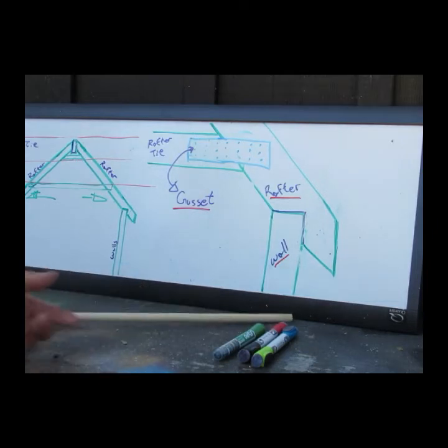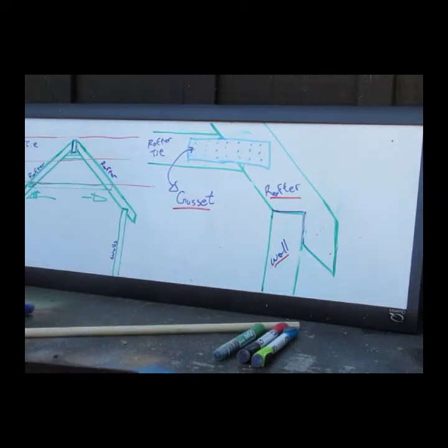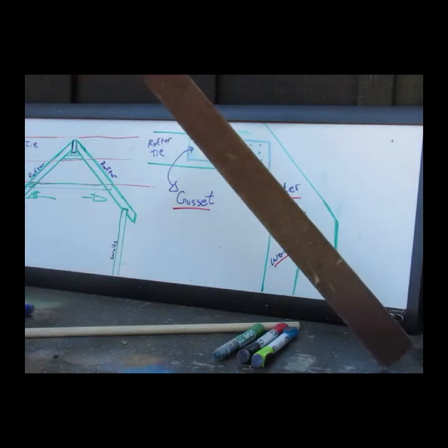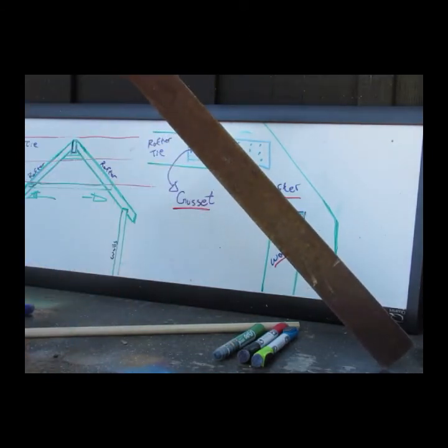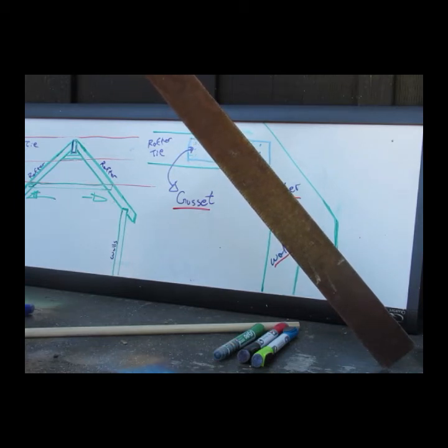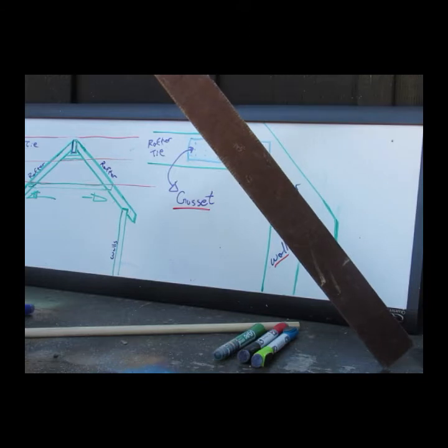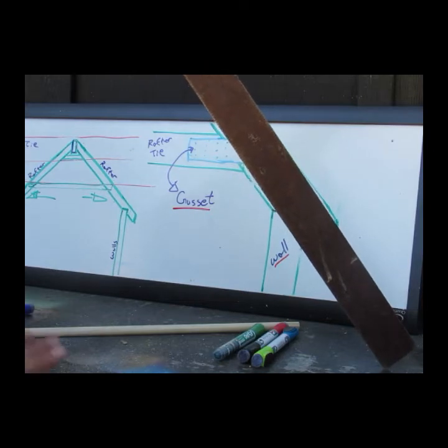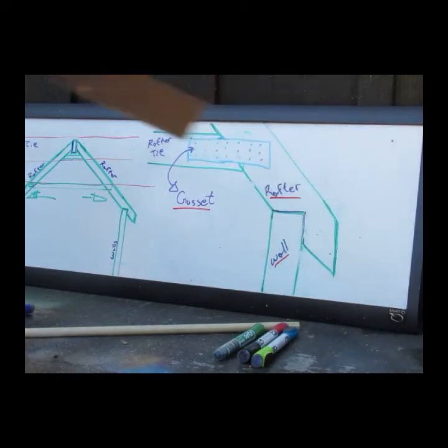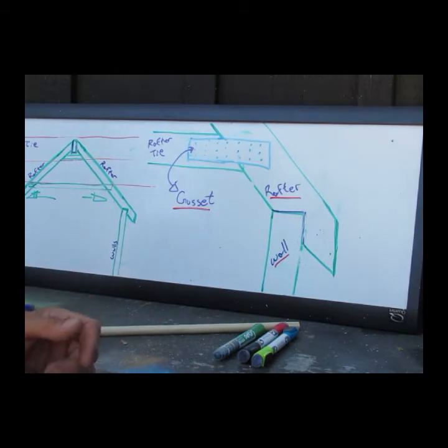There is a whole field of study that we could go into, and have an entire course on how to properly use a framing square. All the notations on this, a full course could be given on how to properly use it for setting up stairs, the rise and run of the stairs, how to notch out your stringers, or how to cut the bird's mouth correctly on the rafters. The best way to do it for us is to take it one step at a time: cut one, make sure it fits perfect, and then just trace for all the rest.